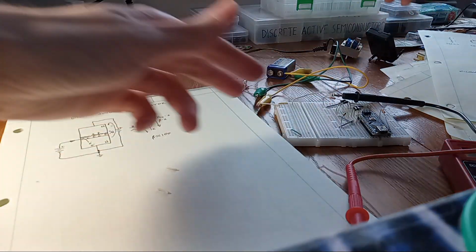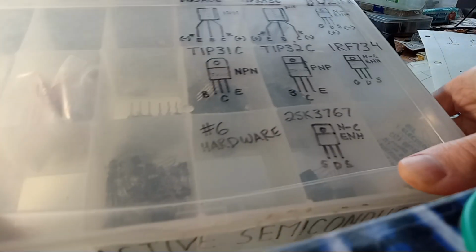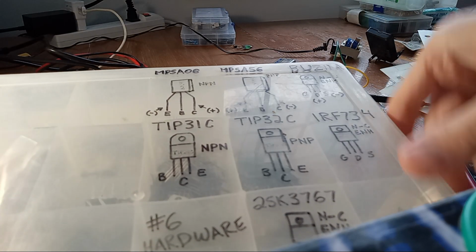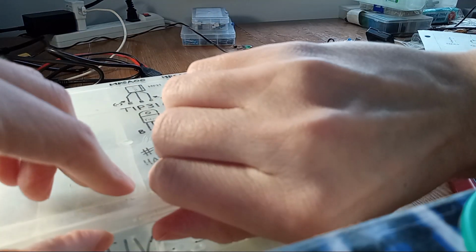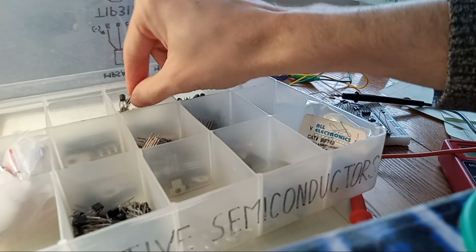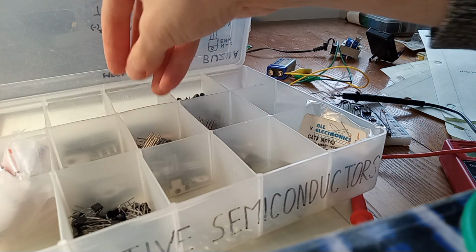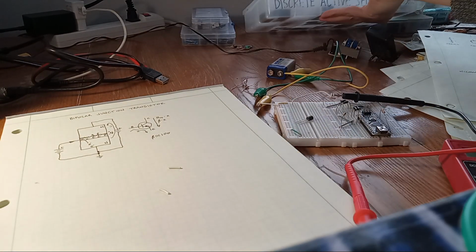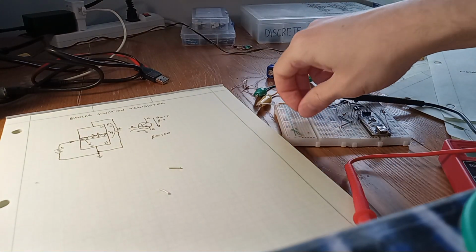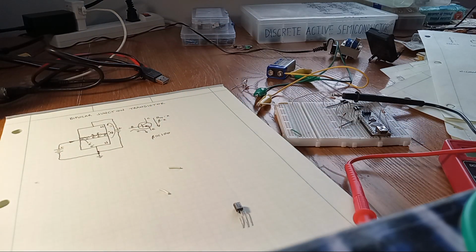So, there are, of course, a wide variety of transistors available. I'm going to demonstrate with the MPS A06 NPN transistor. This transistor has a typical gain of about 200. You should bear in mind that the beta or gain or HFE, which are all synonyms, that factor of a transistor is highly variable. In fact, I can just pull up the data sheet.